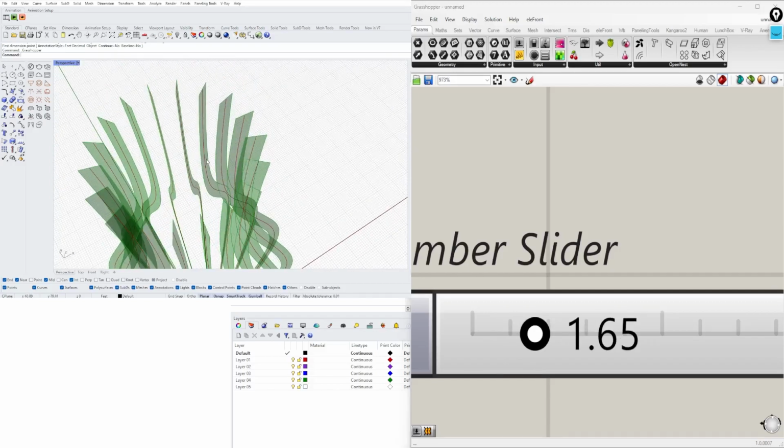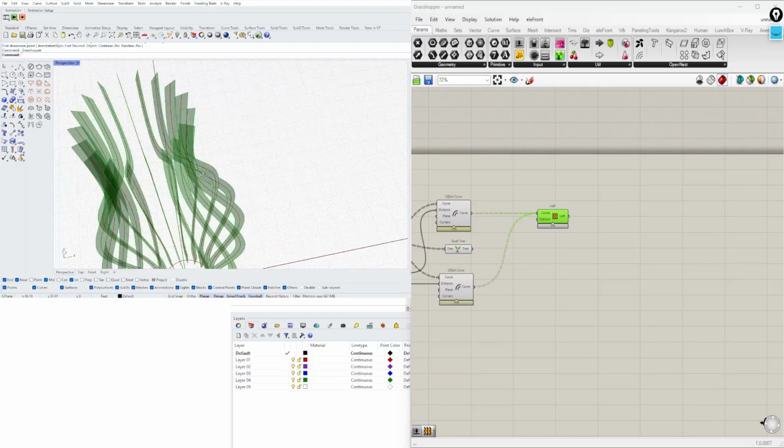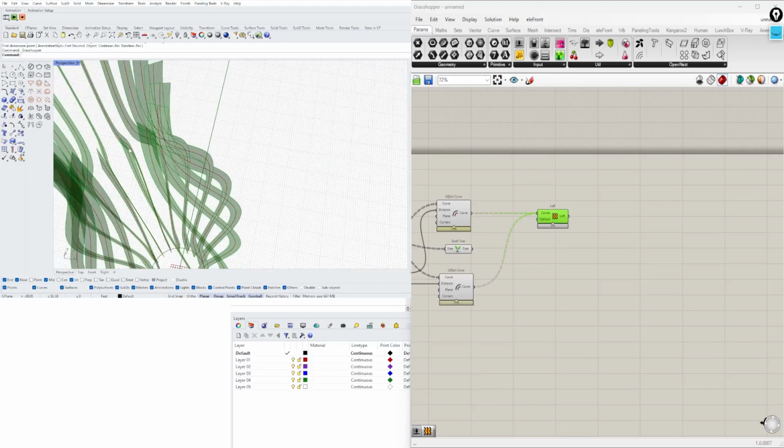We're going to be doing the same thing with the surfaces to create some thickness to it. We need to extrude or move perpendicular to the surface and then extrude the other way by 2.